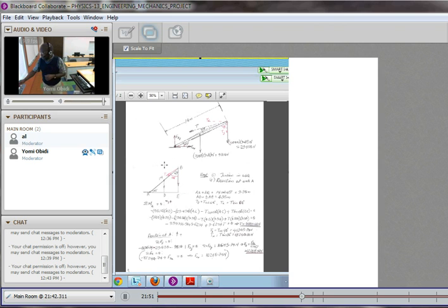Actually, the ideal way to get this done is to find the forces in the Y direction and the forces in the X direction, and have Y over X, and that should give us about 46 degrees, which is a little more than this one. What I've done is an approximate value here, because the positioning in this particular design is such that the resultant force, which ideally is something like this, is acting very close to this. We do an approximation there.